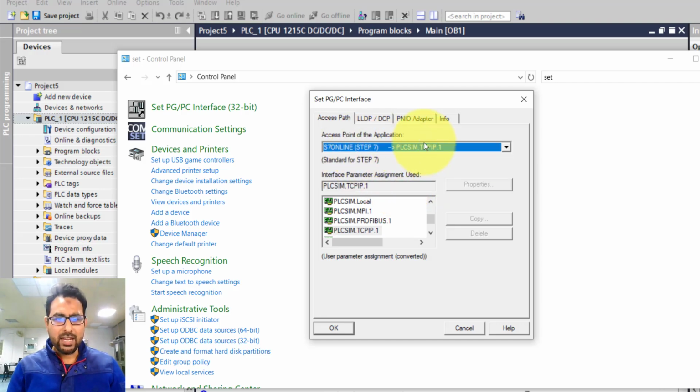Then on this side we want to connect it to our Ethernet card because that's where the real PLC is attached. So the HMI will be simulated using this Step 7 system, and it will be connected to our Ethernet, which will be positioned over here. Over here in this section, you can see all the things with which this S7 can attach. You have to search for your Ethernet card. For me, it is this one, Realtek PCI, and you can see three options. If you expand this, you can see that active is written with this third option. So I'm going to select this third one.